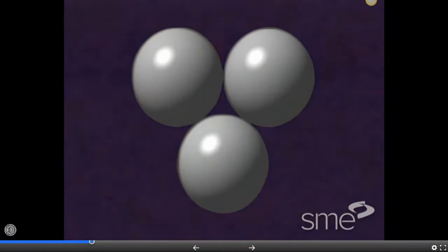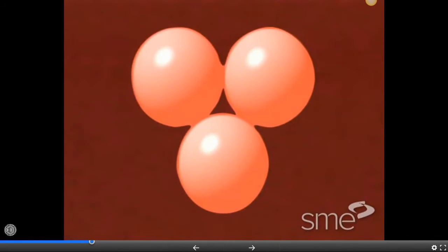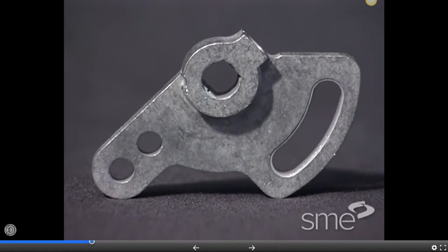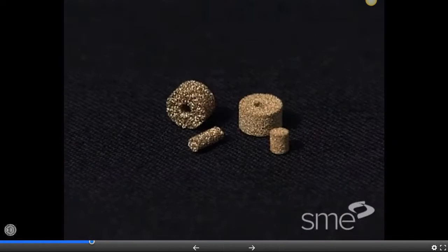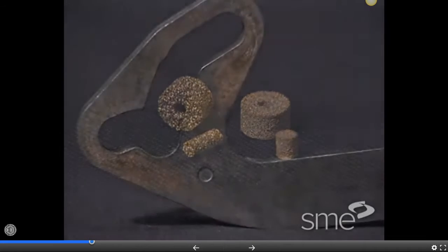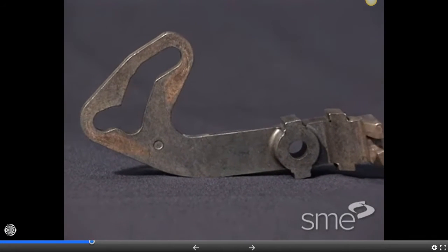During sintering, parts are heated at a temperature below the melting point or range of the base metal, but high enough to metallurgically bond the individual particles. Sintering further densifies the parts, increasing strength. Final part density is extremely important. Although controlled porosity is required and achievable for certain parts, the performance of structural parts increases directly with increasing density.